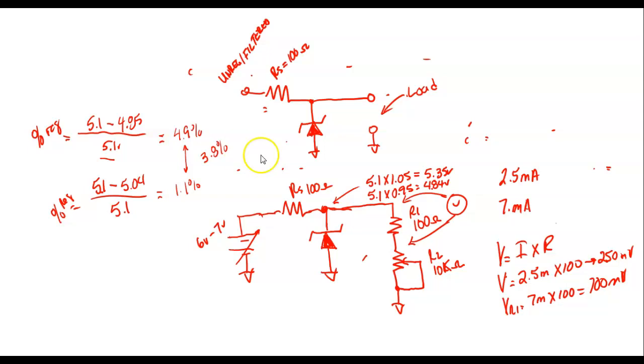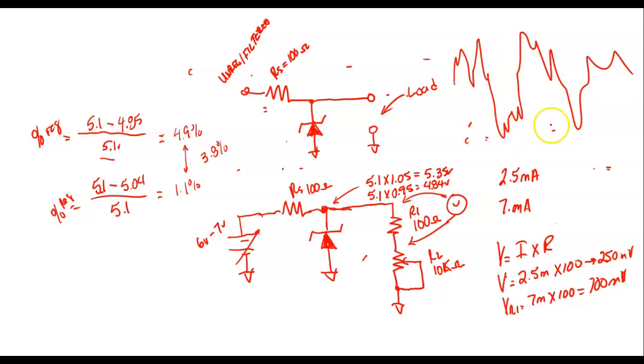It's just like if I was going to design an amplifier that was able to handle certain frequencies, and I look at audio and it's all over the place. So instead of trying to do it with audio, I would get a function generator, put a certain frequency into it, and measure the results. So I put knowns into my design instead of depending on true variables. You understand what I mean?